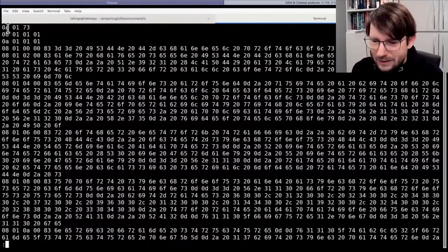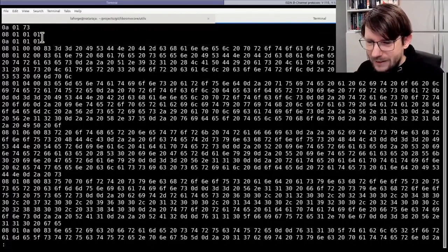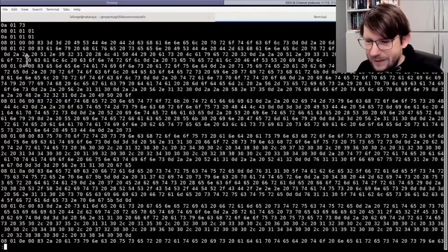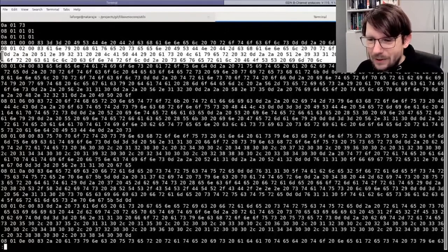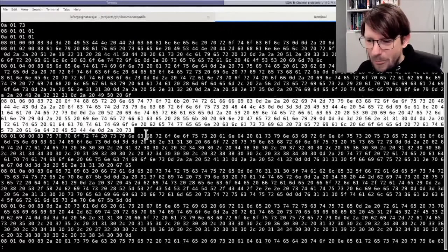So we are seeing only the address and control octets here. I don't recall in V.110 what this now means exactly. I cannot tell you off my head, but we can already see the addresses in V.120. So this is one frame, it's just broken around. So maybe like this, it's easier to see where a new frame starts. So that's one frame. We see the first octet is address, and we see A and 8 always in the address here. So these are the addresses that are used in V.120.